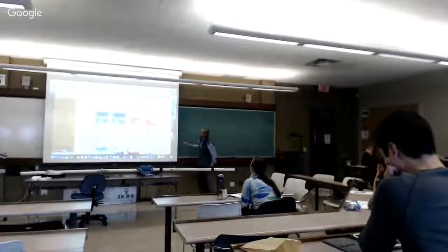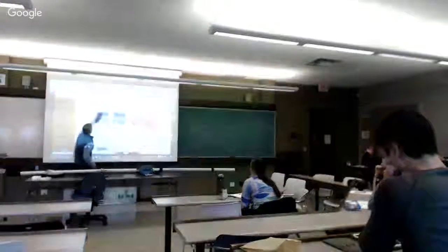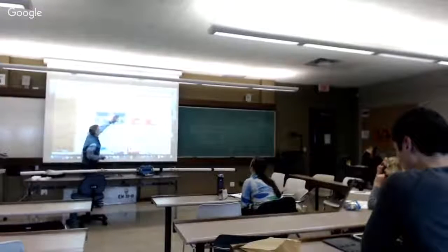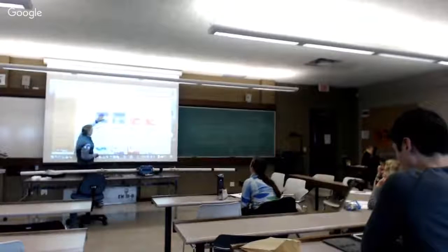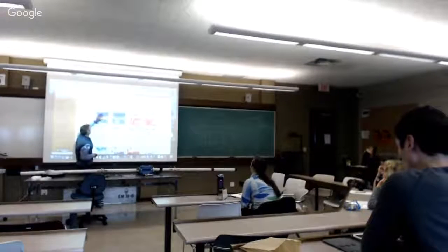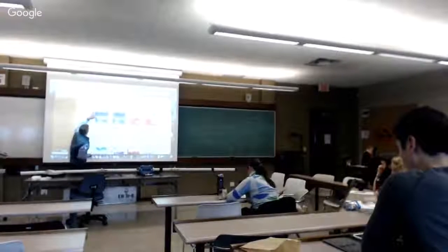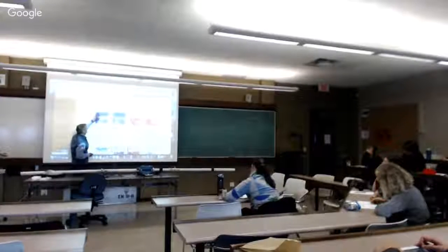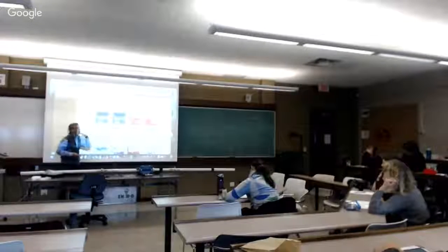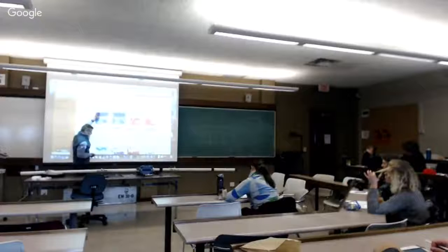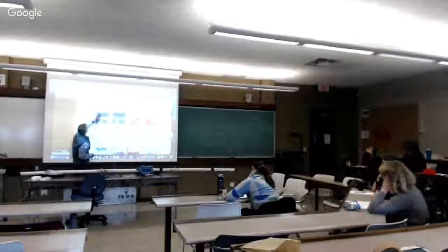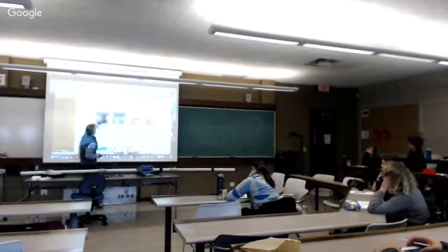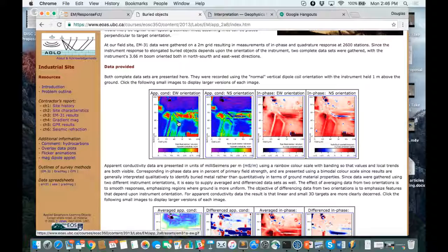On this apparent conductivity plot up here, you can see that there's this blue region up here, very blue, and that indicates that we've got very low apparent conductivities. And when they did the test hole, that test hole was done right up in this region in here, and that's where the oil was. So our idea was that we'd be able to look at where this contaminating or low resistivity region was in this region up here, and compare that with what was obtained from drilling. And for that reason, we outlined a region out here where the oil contaminant was.